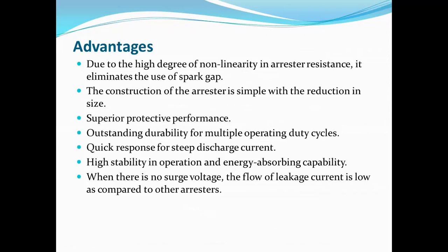Due to the high degree of ionization, there is a high degree of nonlinearity in the arrestor resistance, which eliminates the use of a spark gap. Non-linear characteristic is there, therefore we are not using spark gaps. It has simple construction, the size is also reduced, and it has superior protective performance and quick response